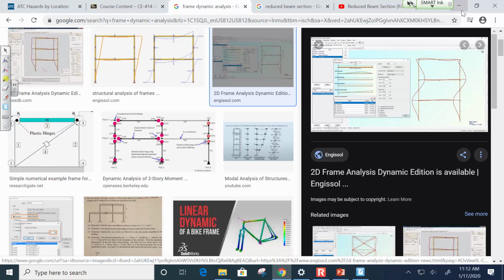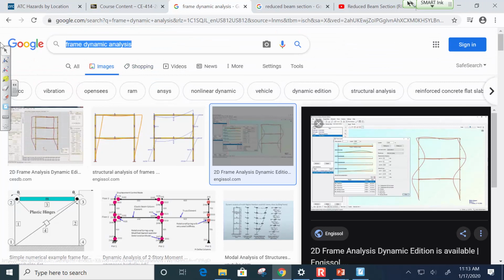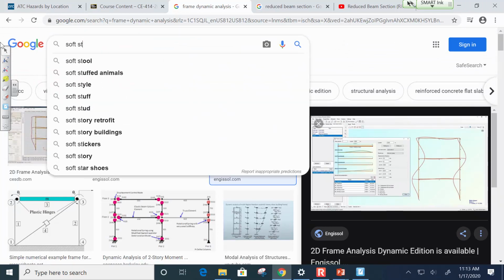So here's the building, okay? There's a couple ways that this building could fail. It's going like this. One of the ways that it could fail is that the columns could fail. If the columns failed, that would be bad, because if the columns failed, the whole building is falling down. We have a name for that in structural engineering, and it's called a soft story collapse.